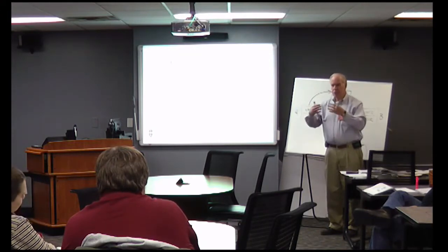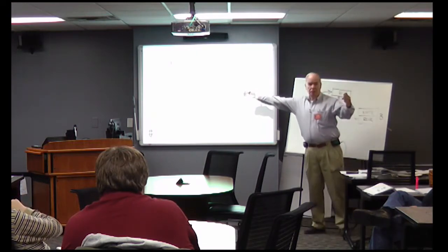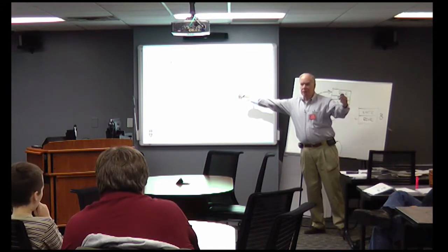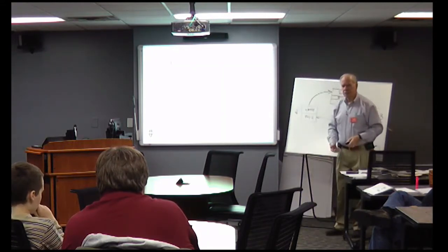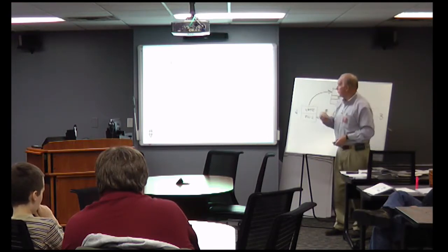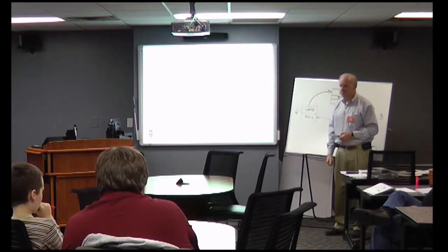Between point A and point B, half a watt might be fine. Between point A and point C, the lowest power you would need to communicate may be 5 watts. So low power, in terms of VHF and UHF communications through repeaters, doesn't really have a characteristic definition.